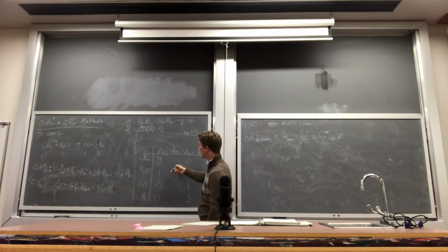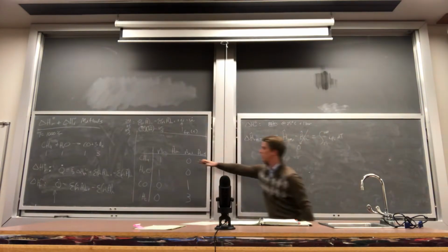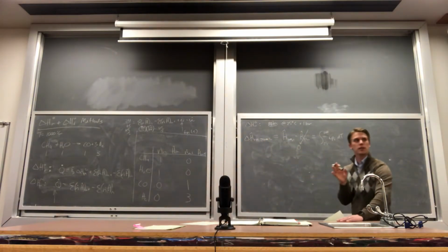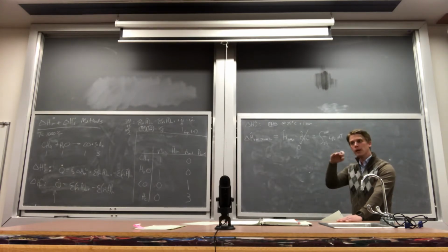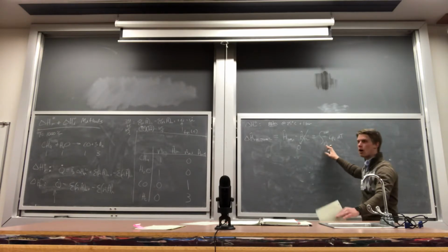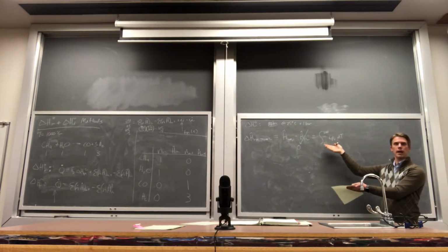Then for every single one of these cells, I just input one equation, and then I copy and paste that equation for every single one. The only thing that's different is the heat of formation values and the A, B, C, D coefficients for the heat capacity correlations. So when you build your table coherently and organized, it means that you really only have to do this one thing. This is all of the analytical input that you have to do with the balancing of a reacting system.